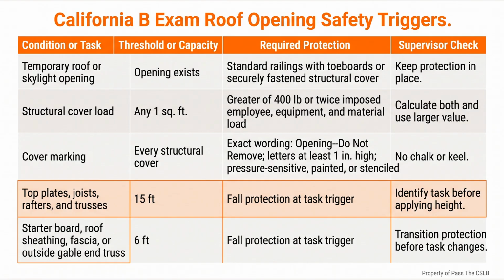Remember, more than 4 feet means doubled headers and trimmers. More than 6 means approved header to trimmer hangers. And more than 12 means added support for the long-tail joist. A single header on a single trimmer also carries the 3-foot bearing condition.